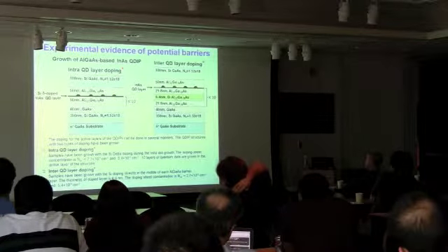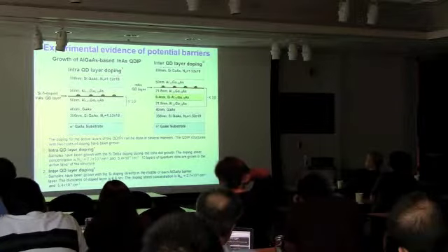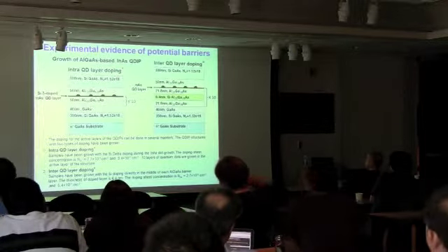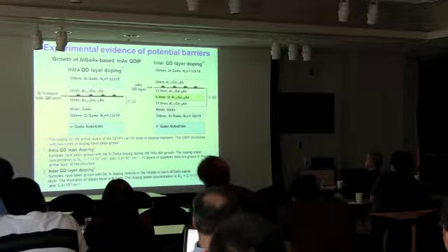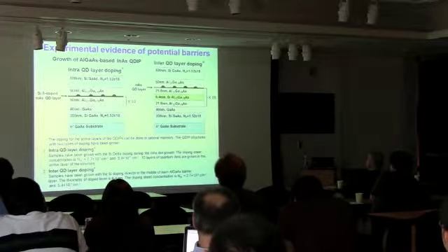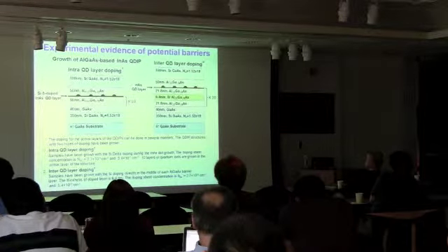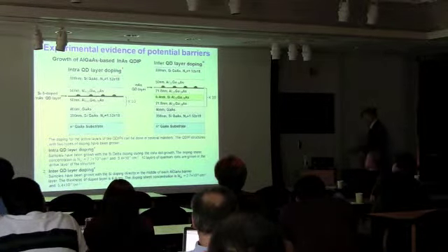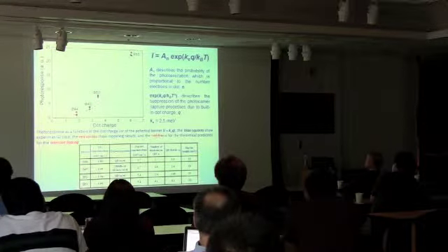So here you see that we grow 10 layers of the dots. It's about 50 nanometers between layers of the dots. It's repeated. The same is here, but in these 50 nanometers, in the middle, we put doping. And now I compare the results of the measurements and what is going on here.